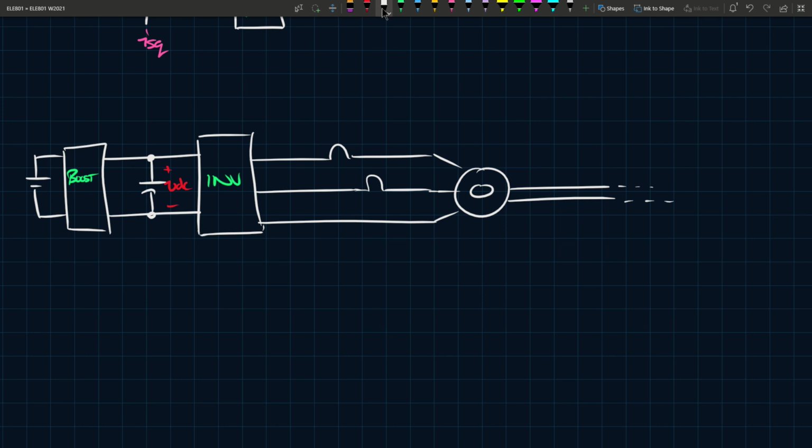And here, to actually control the inverter, you would have to use some type of pulse width modulation, PWM we call it. That doesn't really look like an M, so let's fix that. PWM, and the input to PWM is usually some type of carrier signal. Let's say it's a triangular carrier or a sawtooth, sometimes they make it. The references to the PWM will have to come from VSD and Vsq references, right?